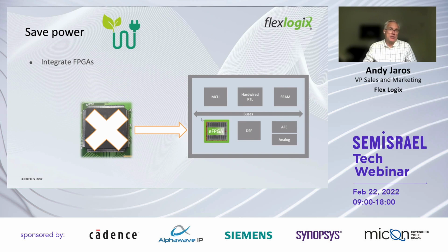In the case of FPGA integration, the amount of SerDes gets reduced because you no longer need the SerDes that are on the FPGA, because they already reside on the ASIC that's being developed. Performance is increased. Reduction in system cost is achieved through reducing testing time, fewer manufacturing failures, and less products to inventory, providing more value to the semiconductor customers.